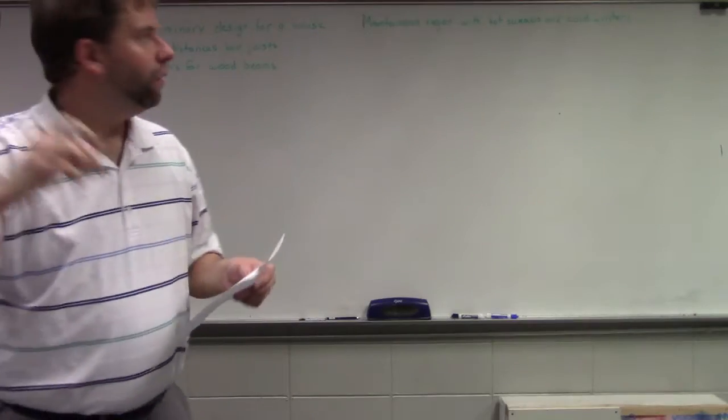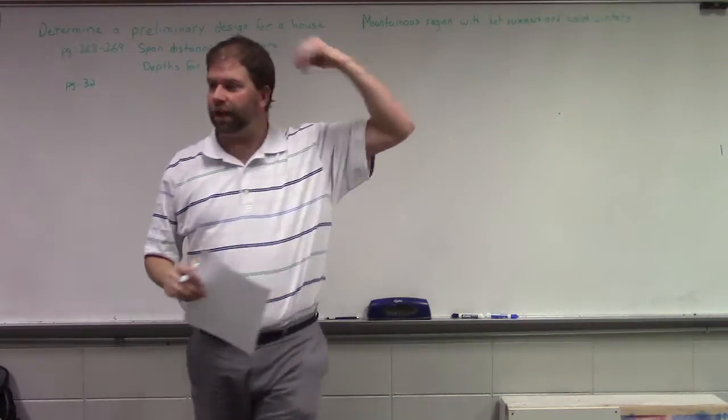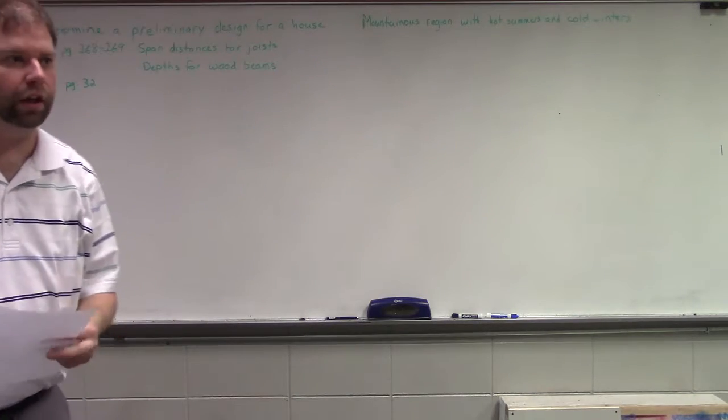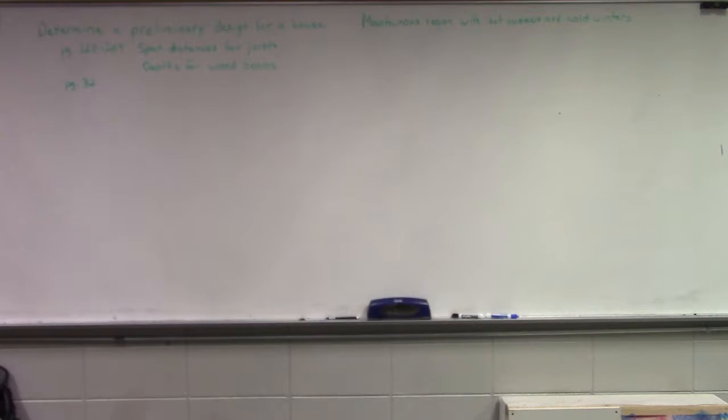We haven't talked about insulation to this point, but what should that be telling us when we're thinking about making a home? R49. What's that? High insulation levels, high R levels. Yep. And so how could we get more insulation in on that exterior wall? Thicker wall. We could use a thicker wall, right? Use 2x6s instead of 2x4s.